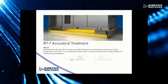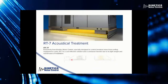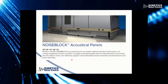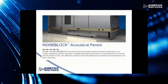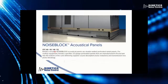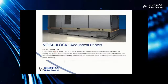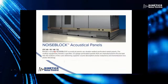For instance, you can go with our cheaper RT7 that gives you an SDC rating up to 37. If that 37 is not high enough, you can jump into our Noise Block, which is our micro-perf sheet metal acoustical noise blocking panels that we use in our barrier wall system. This can lay in the bottom of the curb as well. And based on the different thicknesses available, you can get all the way up to an SDC level of 52 with that one. So again, with the ESSR products, it's very much a design system based on the application and the noise requirements of the installation.